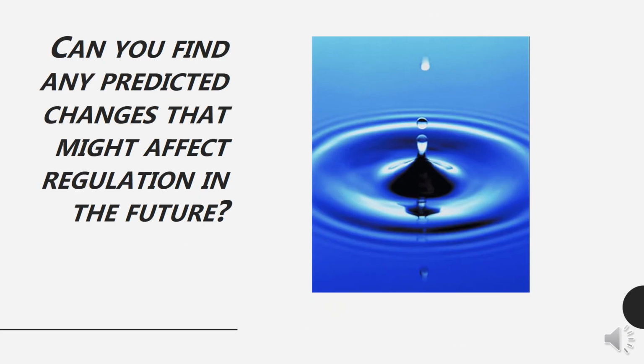Because there have been no human health risks associated with bromide in itself, discharges of bromide to surface waters has not been regulated in the United States. However, an accumulation of scientific evidence over the past 40 years has identified bromide as an important precursor of disinfection byproducts. Brominated DBPs, again, are more toxic than their chlorinated analogs, meaning that there's a potentially greater human health risk associated with consuming water containing brominated DBPs. Greater source water bromide levels can also increase the formation of unregulated classes of DBPs and potentially be more problematic than regulated species.